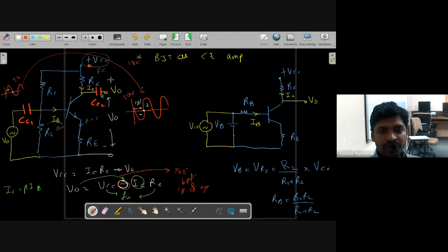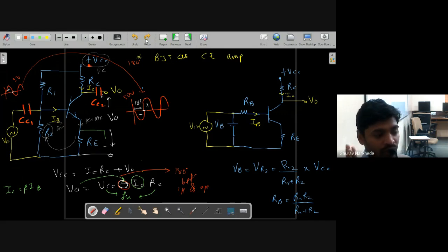So in RE also there will be two components flowing, the AC component as well as the DC component, and then this RE will provide a feedback path to the current, and this AC plus DC will go inside the transistor, right? That will again cause distortion and noise. So we want to avoid giving the feedback from the RE to the input of the transistor, right?